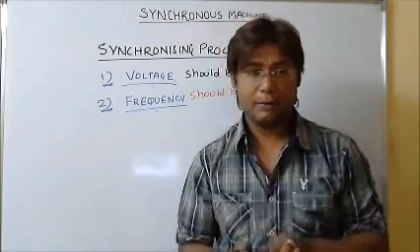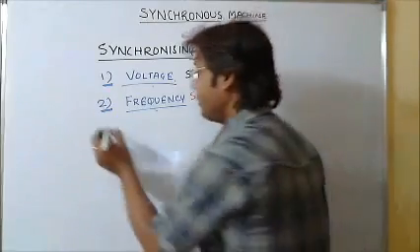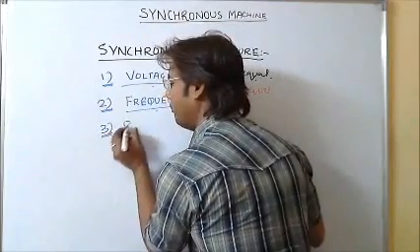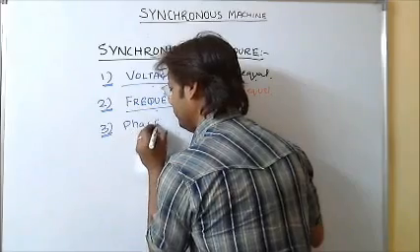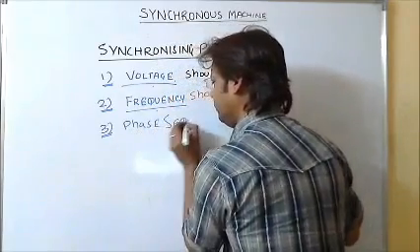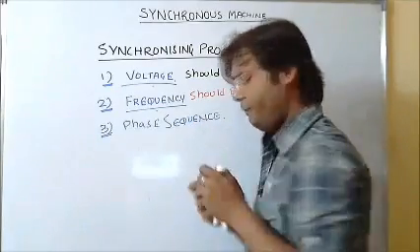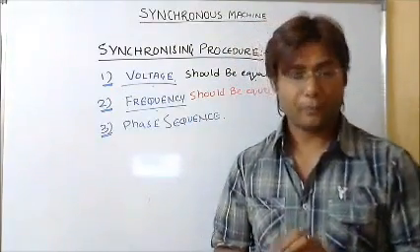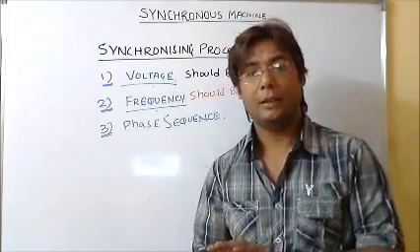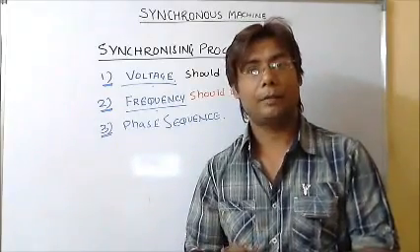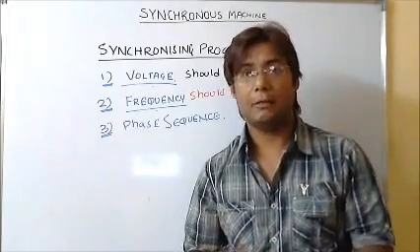The third thing, which is very important, is called the phase sequence. The phase sequence of the incoming generator must be the same as that of the bus bar.